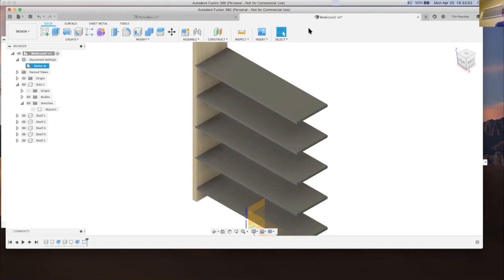And that's a very useful thing to do in a lot of cases. The issue I have here is Fusion 360 isn't robust enough to pattern the component subtraction. So I would have to do it for each shelf. And then it breaks if I change the number of shelves. So that doesn't give me a robust model. I like that approach from a philosophical point of view, but it just doesn't cut it for me.